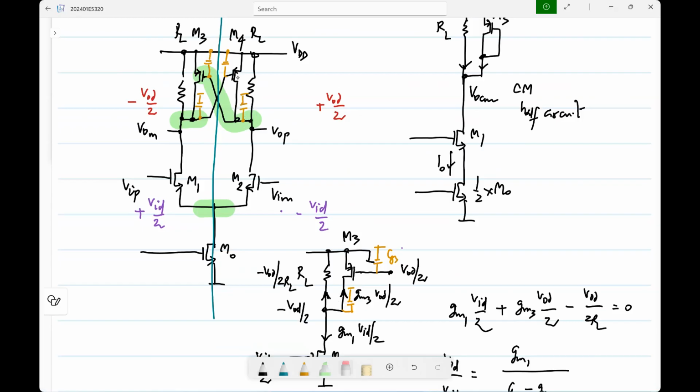If you have only the corresponding nodes connected, the nodes along the line of symmetry will have 0 voltage. So any parasitic capacitance from that node will have no effect in the differential picture. In the common mode, they will not be separated anyway. I don't think there is any problem with the common mode.